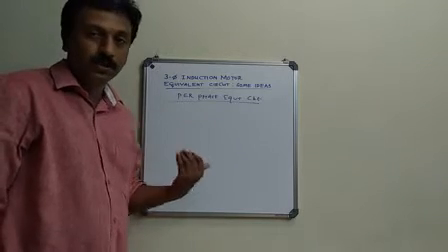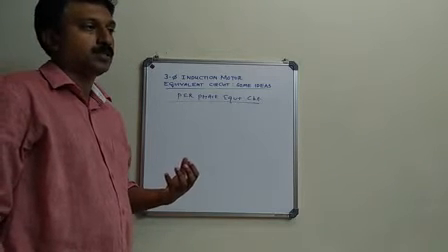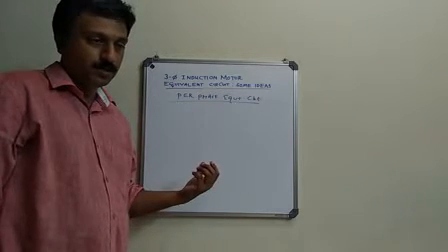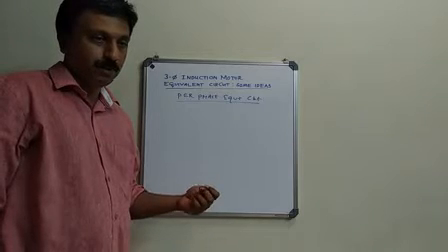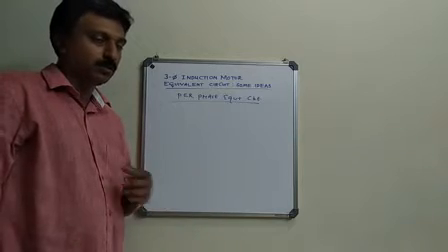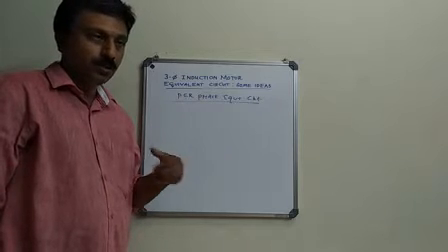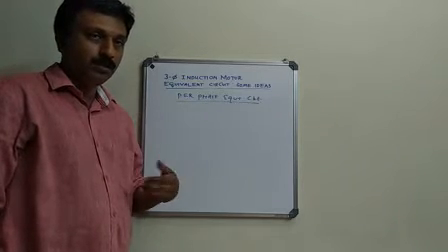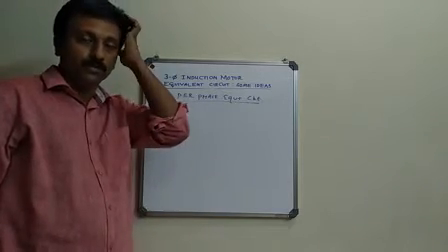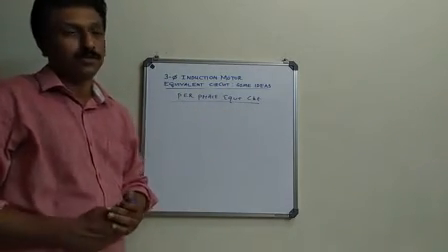If you draw a three-phase equivalent circuit, it is very difficult to interpret and get meaningful information. Since everything is balanced, the windings and the supply in a three-phase induction motor, if you draw it for a single phase, you can derive the three-phase quantities from that single phase circuit. So that is the idea. So we will be drawing a per phase equivalent circuit.